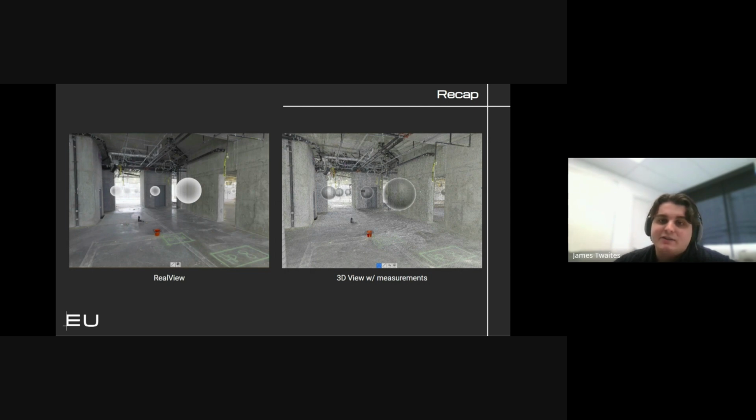And then on the right is the point cloud data, which is not like a photograph. It's more like the output of a total station. Imagine if at each of these orbs, there are two data sets. There's 360-degree photography, and then there's also LiDAR. So it's as if you set up your total station at each orb and took hundreds of thousands of points. So that way, instead of listing everything you could possibly want to measure ahead of time and then going and measuring it specifically, you just go out and you measure everything all at once. And then you can extract the information you need from that a la carte.